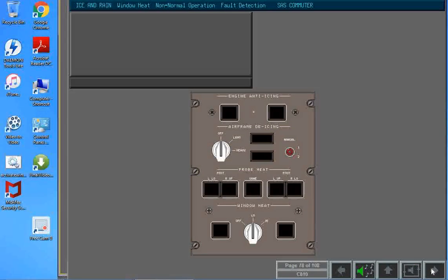A check is performed by check units during the first 3 seconds when the window heat selector is switched to the low or the high position. The check simulates a low window temperature. Therefore, the relevant temperature control unit switches the window heating on. The check unit examines the current through the window element.